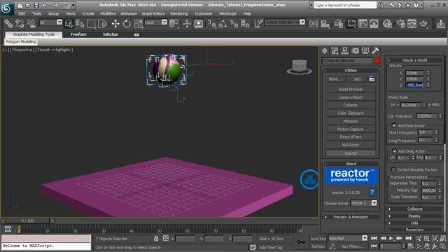That's very near the real Earth gravitational acceleration. And we have to set the world scale, where 1 meter will be equal to this number in 3ds Max, and we are using the real world scale, so 1 meter will be 100 centimeters in 3ds Max.